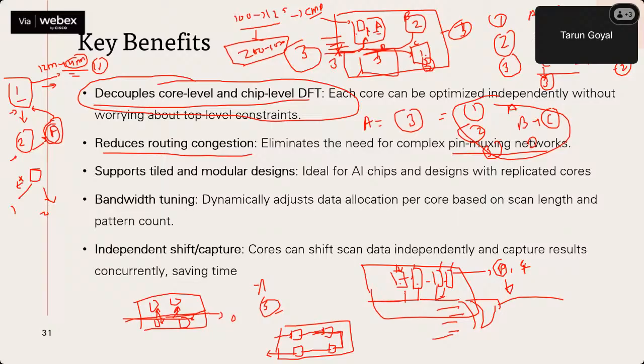So we apply the data, having an on-chip compare. It compares the data. It's a hardware addition, but it's using 4 cores, 10 cores, 20 cores, right? So now it's one hardware cost for all 20 cores. In that case, we are not getting any scan out, and we are just keeping the same data to all cores, broadcasting, and we are comparing on die, just giving pass/fail. If we need to expose the scan out, we can do that for debug.